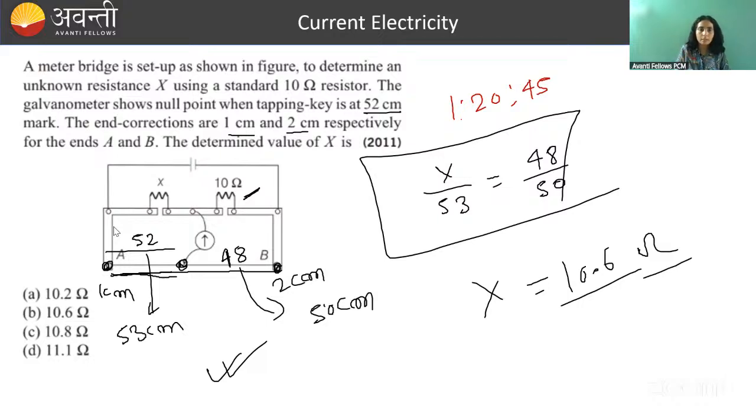Because directly, the length I have written, because length is directly proportional to the resistance. Here what will you write? Rho L by A. Here also rho L by A. Area of cross section throughout is same of the wire, nothing is given like that. Wire is of same material, rho is same, so everything will get cancelled. That is why I simply wrote the length.